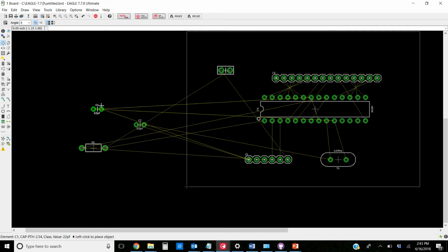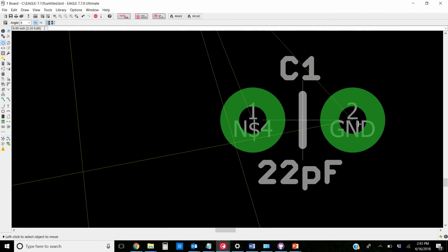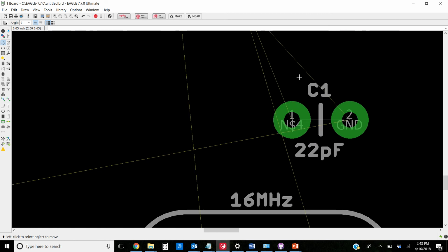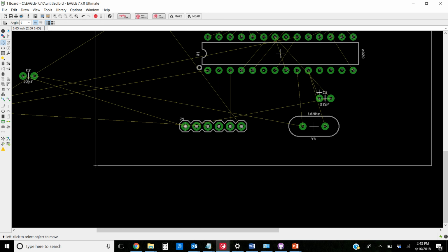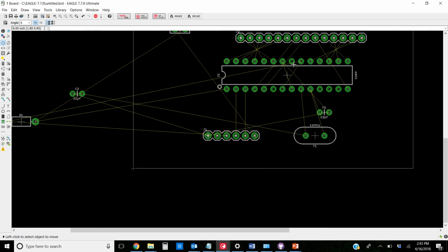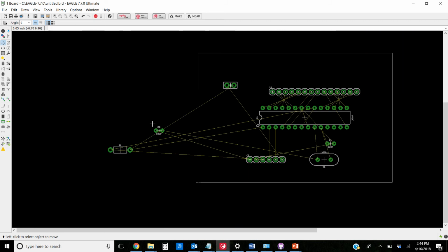So then we can start picking off our parts here, and you can start to see where these things actually go to. Now, I'll show you a little trick here. Some of these parts, for example, when I get close to it, you can see GND or ground is what this line is going to. And ground, we haven't really defined a ground plane, so it's trying to run that wire to another individual ground. So this isn't really a wire that we're going to route, and I'll show you how that works later. We're going to end up doing a copper pour.